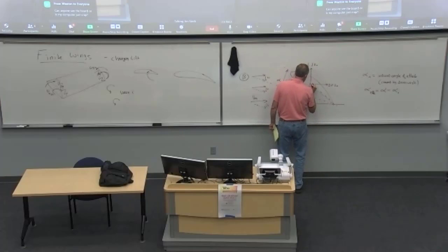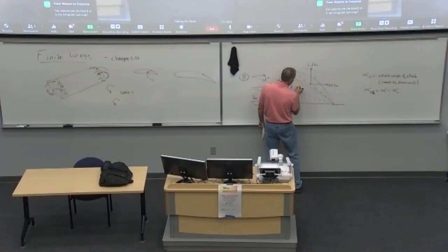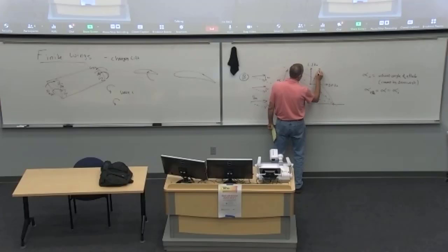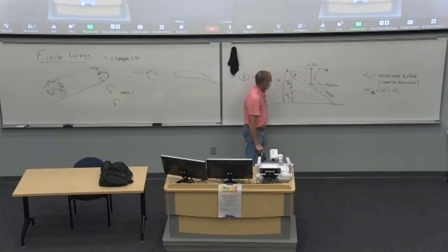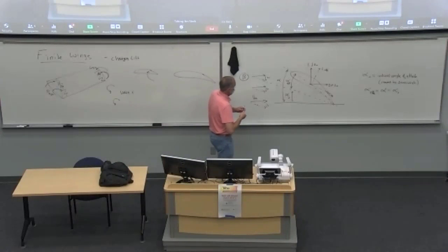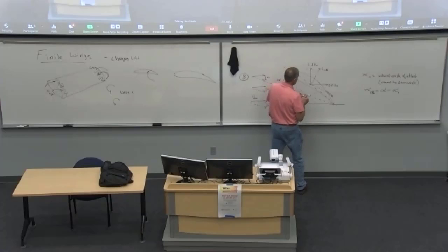So then the lift with the downwash is going to be perpendicular to that free stream, which is affected by the downwash. So there's the lift, the effective lift. And the drag tilts as well. So the effective drag, dotted line. And notice things happen now. Because of the downwash, we get a part of the lift vector acting in the drag direction.